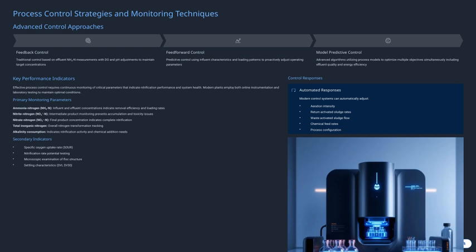When issues occur, troubleshooting involves diagnosing symptoms, say, high effluent NH₃-N or nitrite accumulation, and identifying likely causes through diagnostic tests like SRT calculations or microscopic analysis. Corrective actions might include reducing wasting, increasing aeration, or adjusting pH levels. Successful process control integrates real-time monitoring, predictive modeling, and operator expertise.